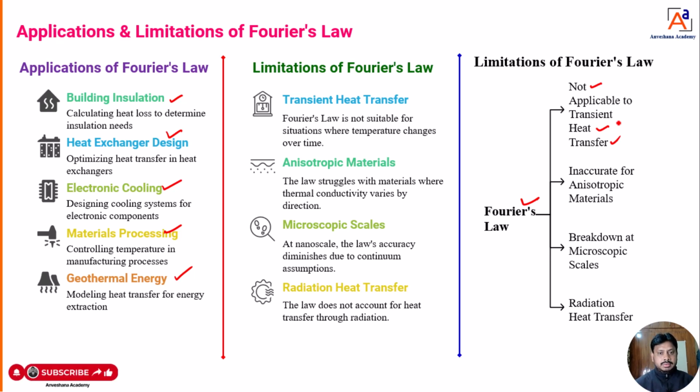Fourier's law is only for steady state conduction. Steady state means the temperature variations remain the same at any interval of time. If the temperature varies with respect to time, that is transient, and for those applications we can't use Fourier's law. That is one limitation.